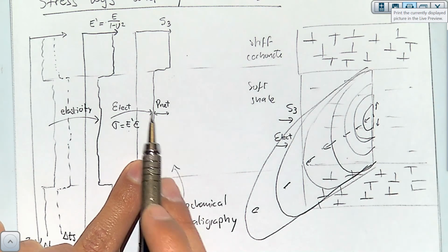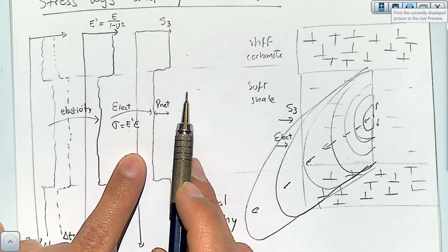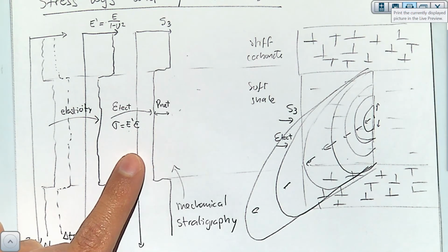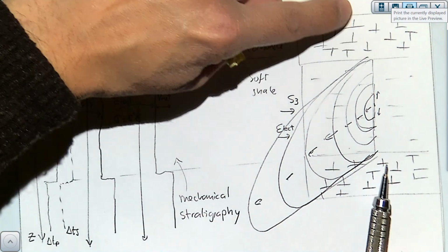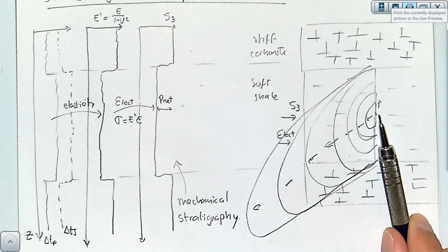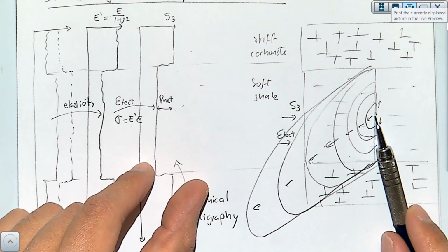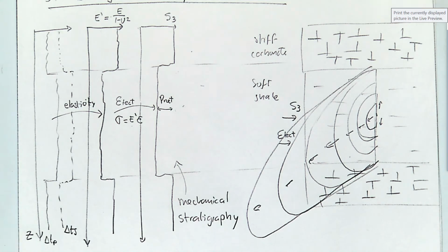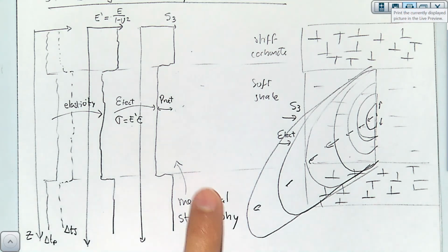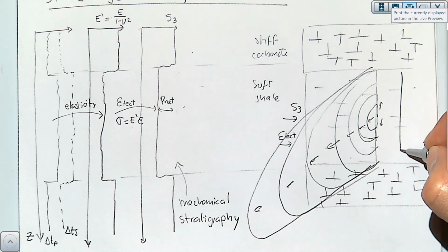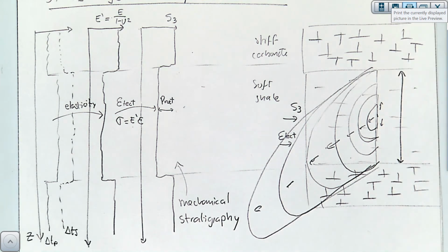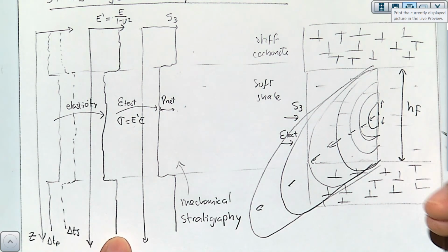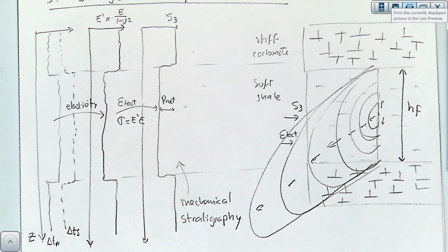So if the net pressure were to grow and exceed this amount, then it could go into the other layers. And for example, at the point in which the net pressure in this location is higher than the initial contrast, it could grow into the other layers and find some other limit in the fracture height. But for now, let's just limit this to that. And if we keep the net pressure within those limits, then this is going to be the hydraulic fracture height.